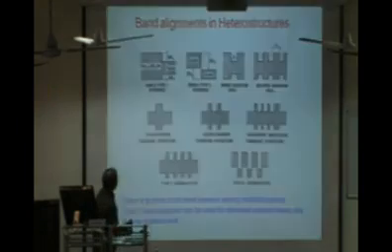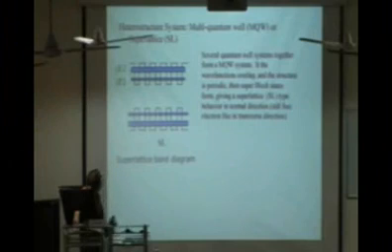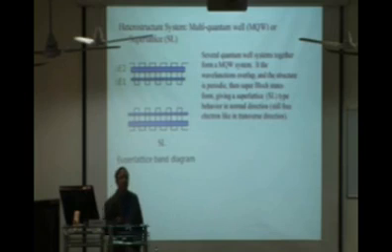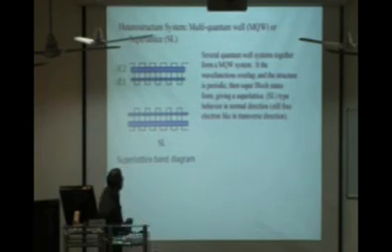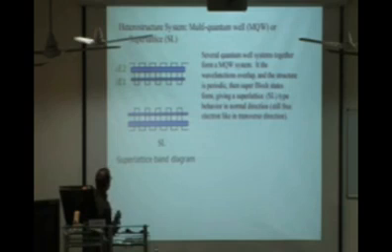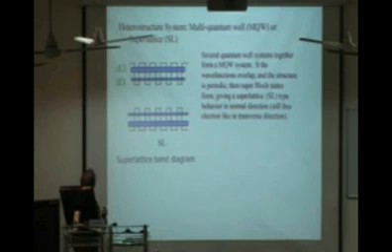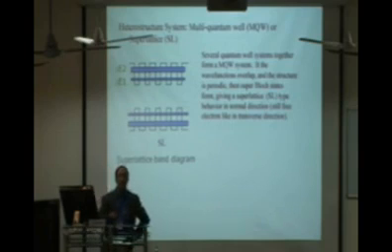So what you get in this kind of superlattice is something like this. In fact, if you put several quantum wells, 50, 100, 500, there is no limit. The only limit is how much you can grow, what your growth rate is, and how uniform the barrier and the well are. It's very difficult to grow with uniformity over a large number of quantum wells. So if you put this together, the wave functions in each quantum well start overlapping, and we again get Bloch oscillations of the super Bloch states in these quantum wells.